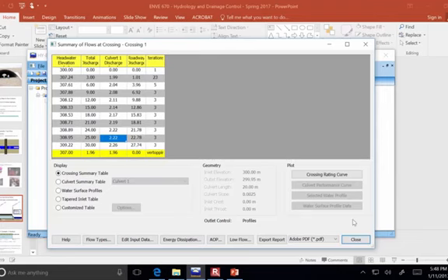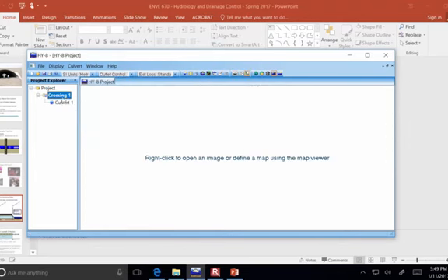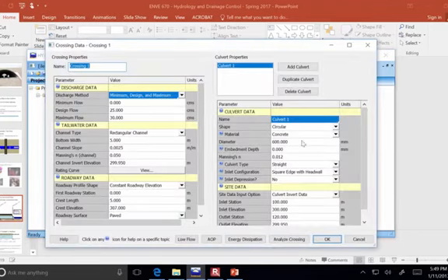So design is an iterative process. It's that optimization process of doing things over and over again until you have a solution that's just barely good enough. You know, the most economical solution is the thing that's just barely good enough to satisfy the objectives. So let's play around with this and see. From the drawing, you can see the headwater is higher than the roadway profile. Let's go back to the parameters of the crossing.